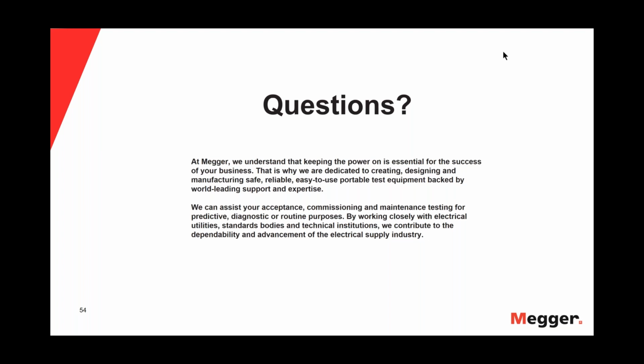Well, so you have an old cable, service age cable, that has developed a fault. So I understand this question as, in the course of finding that fault, could you do more harm to the cable? And that question has to be answered yes, because especially if you do fault locate not using a TDR, just thumping, and you have to thump for a whole day on this cable, you might push one of these other spots that are very close to fail, you might even have pushed it closer to real failure.